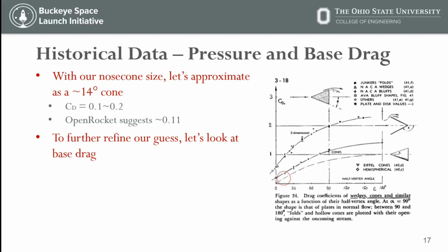An ogive nose cone is, like you said, there's not really a lot of benefits when you're trying to optimize a vehicle for supersonic flight and you're not as worried about subsonic flight. Von Karman nose cone, I believe it minimizes drag over, is it a volume or an area? I don't remember exactly what it is.